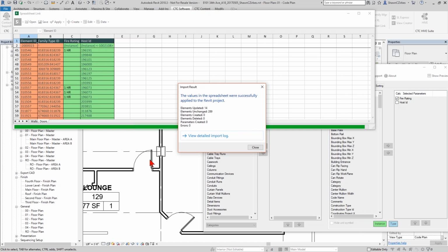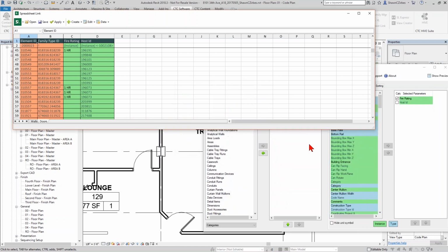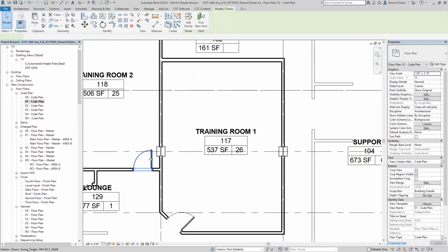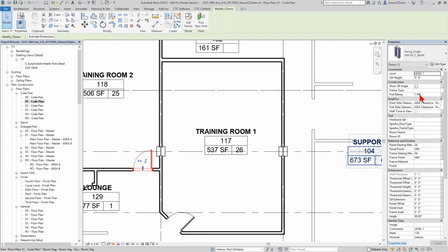I probably should have shown you this first, but none of these doors had any fire ratings in that instance parameter. And right now, if I click on, say, this door right here, my instance parameter fire rating is 1 hour. It fills this property out. It's not using a global parameter because my global parameter process can't reference the wall and read its fire rating. It's just a value that's a calculation that I put in. But this way I was actually able to take an element, have it read something else.